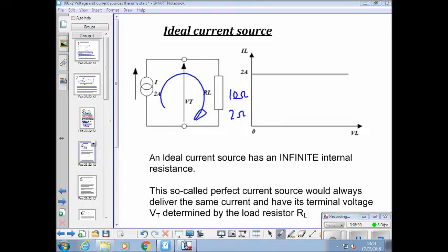You must remember that it is impossible. We can design power supplies that will, between a certain range of currents, hold the voltage stable. So we can say we want to stabilise the voltage at 12 volts regardless of current, and it will do so between a certain range of currents, let's say 0 to 2 amps, a stable 12 volts. What that means is if you go above the 2 amps, you're going to start losing voltage. Okay?